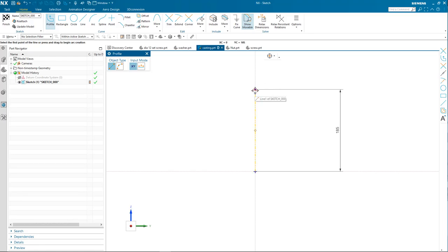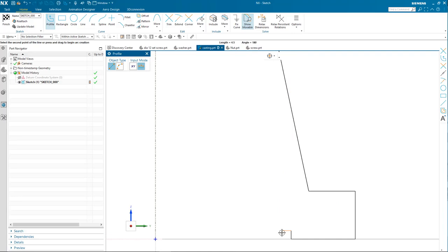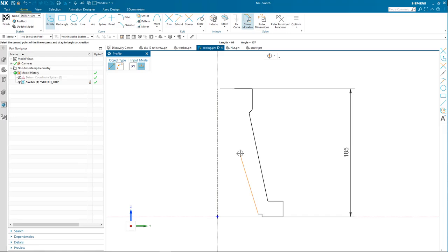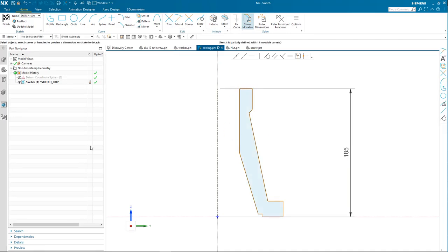So I'm going to grab onto that end line, and then somewhere along the parallel area, a little maybe too far out, coming a little closer, I'm just going to start drawing a rough sketch of what this geometry will look like. From here, using the profile method, I just connect all the dots together where I think each one of those locations will be. At the end, those two lines are not parallel to each other, so I'm going to extend that. I don't worry about anything that goes beyond, so those two lines I can just trim off.